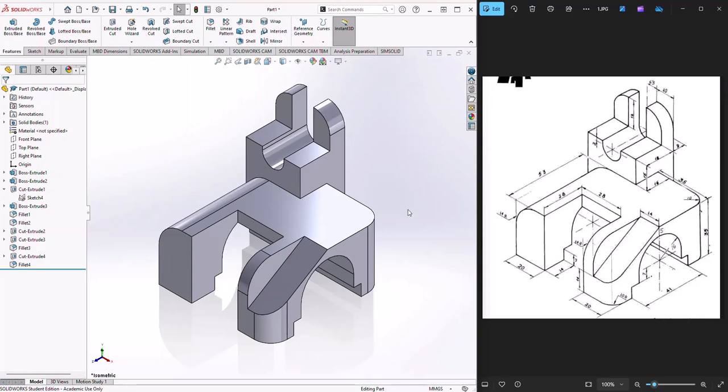I need you to note that this is something that I did not discuss before. Look here along these surfaces. You'll see that we have these lines over here, and then again here we have these two lines, a line here, a line here, here, here, and here. And these lines you do not see on the actual drawing. These lines are not part of your geometry as a solid model, but they are the separating line between the flat face and the next connected round face, because this is the face that was created using a fillet.